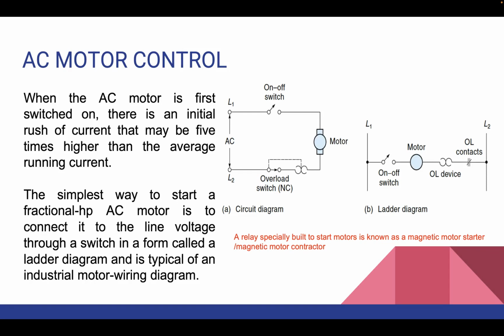However, if the thermal protection resets while the power switch remains on, the motor could suddenly restart, and potentially cause harm to an unsuspecting individual or the person who is operating it. So this is how motor control can work, a simple example of that.